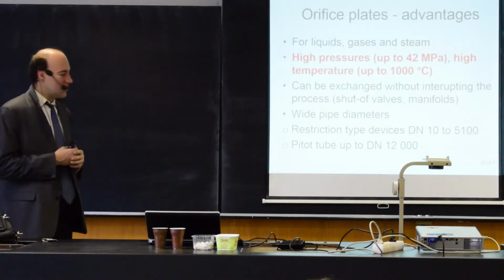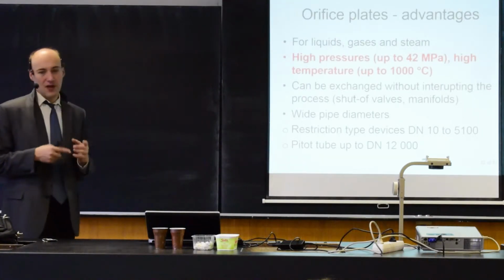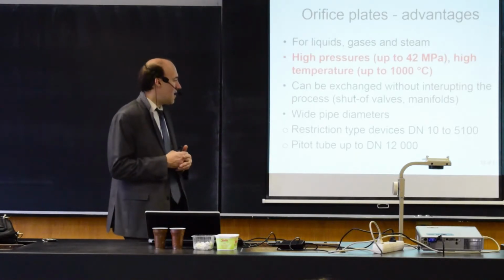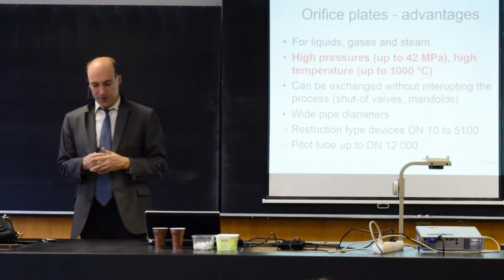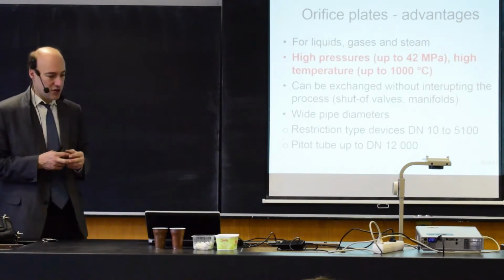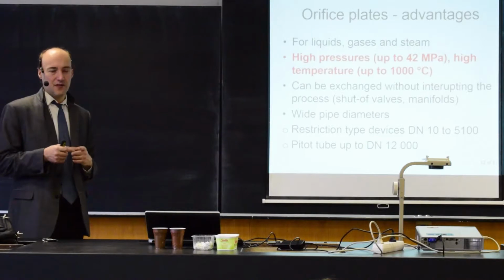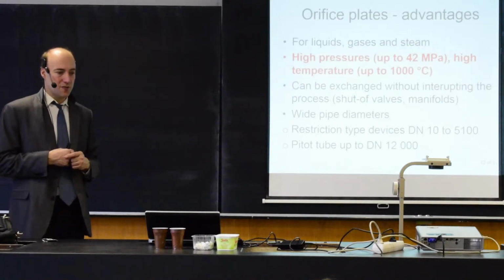It is usable for wide pipe diameters. The standard orifice plates are for diameters larger than 50 millimeters. So if it's larger than 50 millimeters, you can use a standard orifice plate.